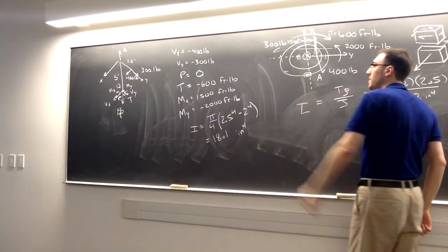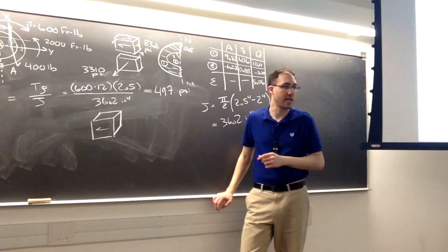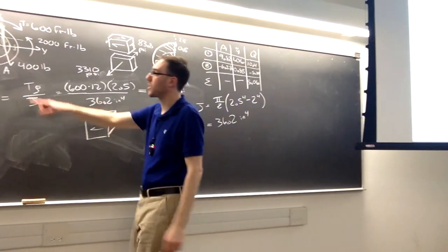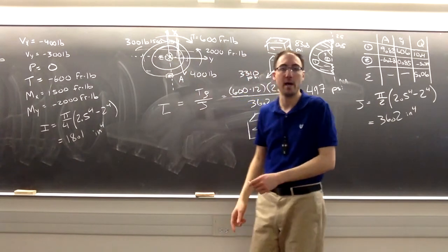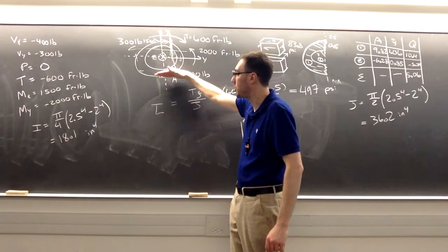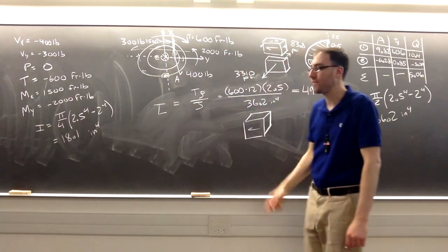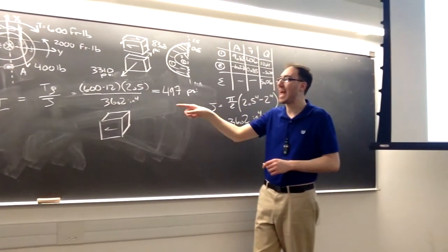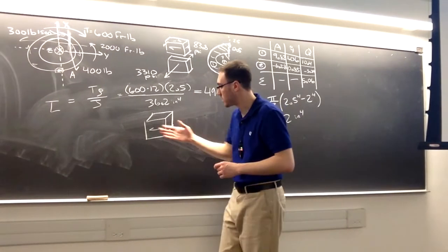So it's always going to be in a direction tangent to the circle, I guess is the best way to think of it. So when we're at the bottom end, it's going to be based on is this T clockwise or counterclockwise. So at the bottom, this piece, due to that torsion, is going to be shifted tangent to the circle, so a little bit to the left is that shift. So that's the direction at A due to that torque. So on the front face, it's being pulled to the left.